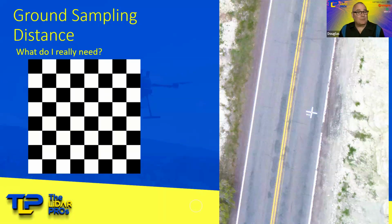Why is this important? Because the lower we go in ground sampling distance, in other words, the better sample we achieve, the lower we have to fly our aircraft. The lower we fly our aircraft means the longer our flight time is going to be. So there's a balancing act between that conversation of GSD, or ground sampling distance, and altitude and efficiency of our overall flight. So bear in mind that the amount of time that's going to be vested is going to be a pretty big consideration.